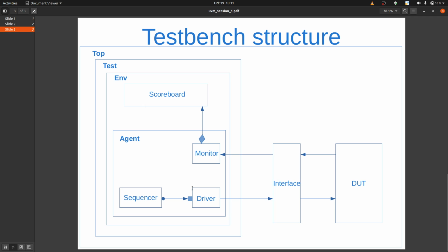Now my predictor has the input, and when the output comes from the DUT and is captured by the monitor, the monitor sends it to our golden model. Now this has the output of our DUT for the same input, but its own logic generates a separate output as per the input provided by the driver, and it compares both outputs, whether they are the same or different. So that was the way in SystemVerilog to verify whether the output is correct or not.